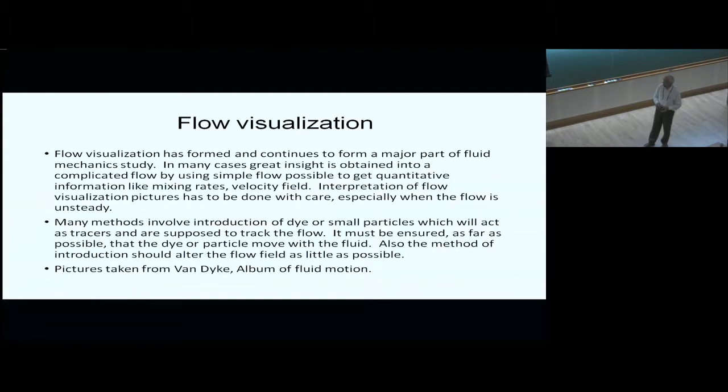But one has to be very careful in interpreting the images, especially when the flow is unsteady, because you can get very wrong interpretations by just looking at the picture. And most of the methods basically involve introducing some sort of foreign object like a dye or a small particle, and this is like a tracer which is supposed to follow the flow.